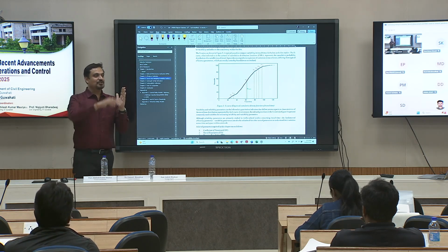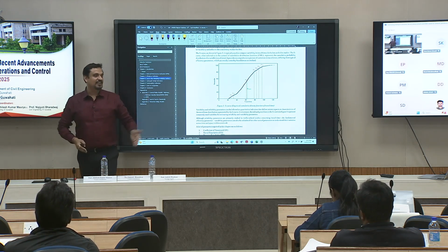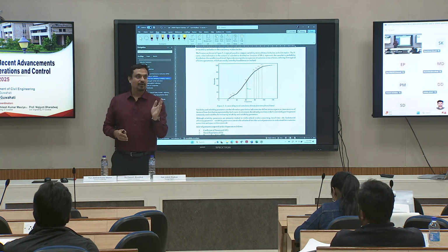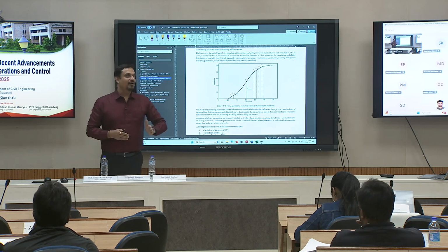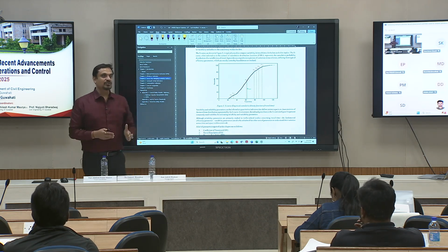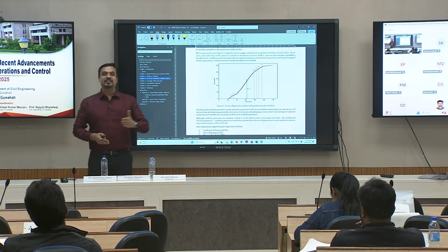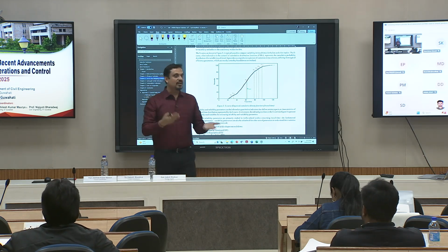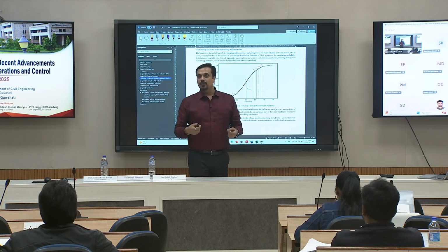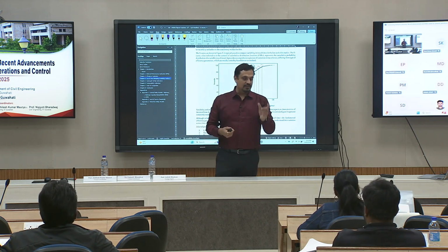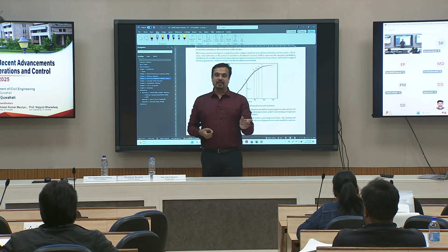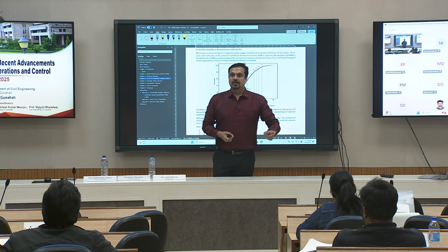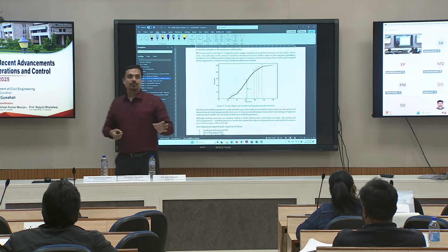You will never have a perfect straight line like this. It's almost impossible because of the stochasticity in the system. You can have it on certain public transport routes, definitely, but you will have slight variation because you are at a signal intersection. Depending on the time you hit the intersection, you will easily have a delay of about half of the red time. So half of the red delay you will anyway observe at the intersection.